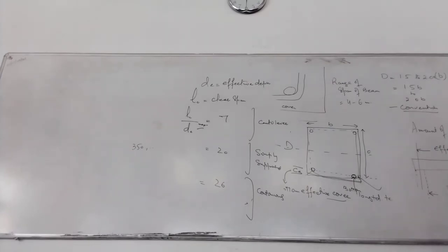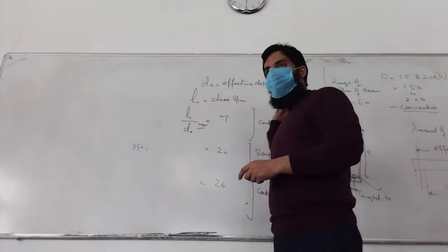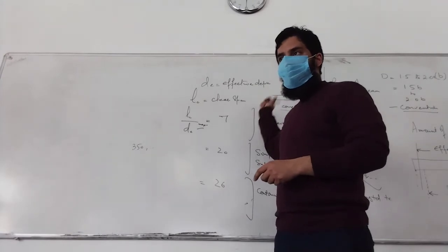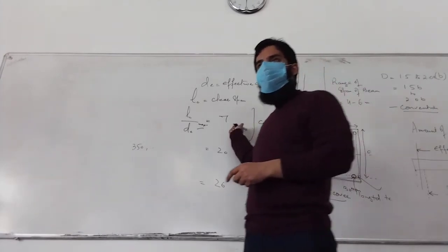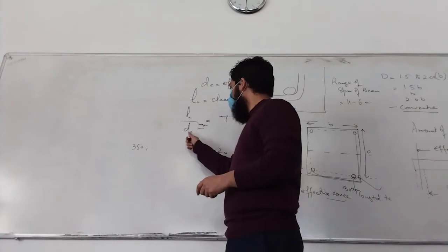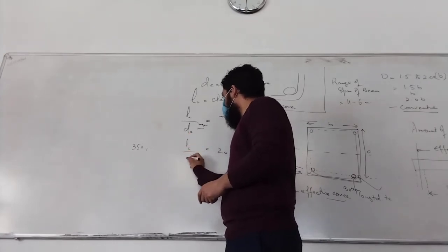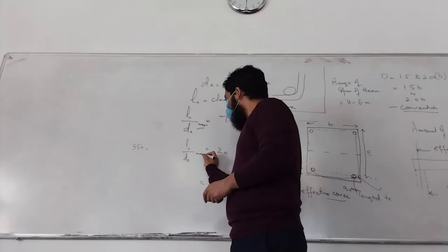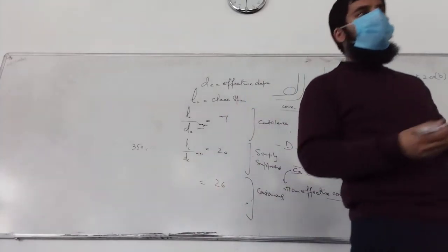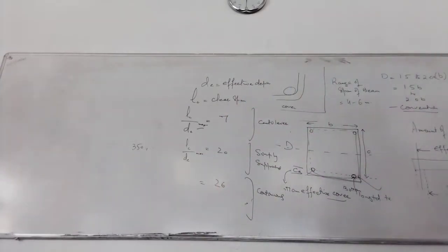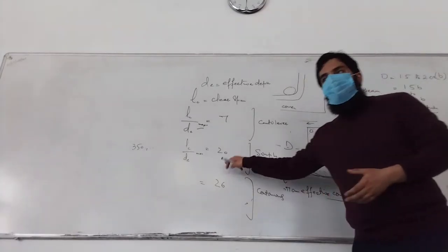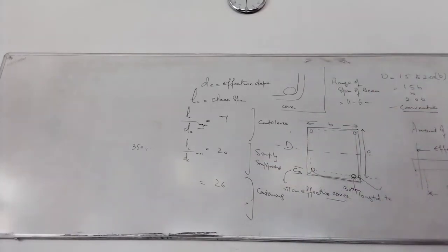Now for simply supported you have a wide range up till 20. If it was 200 or 300 mm, then you are providing the depth. So this will be 300 into 20. So you can easily go till 6 meters in a simply supported for just 200 by 300 beam. 200 is the width and depth is this. So this is how we maintain control on deflection.